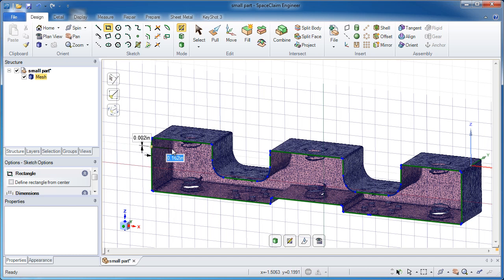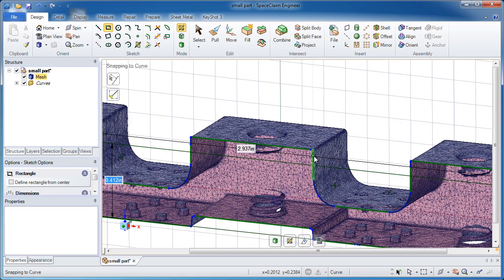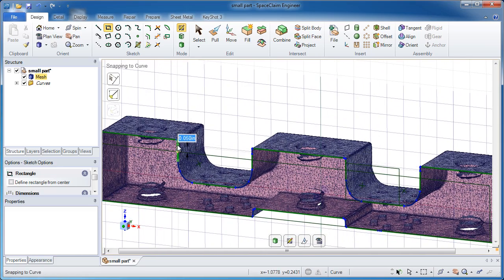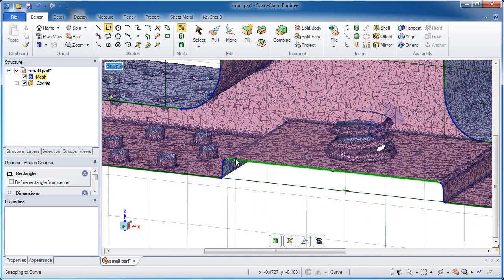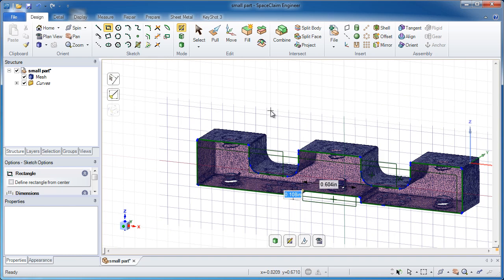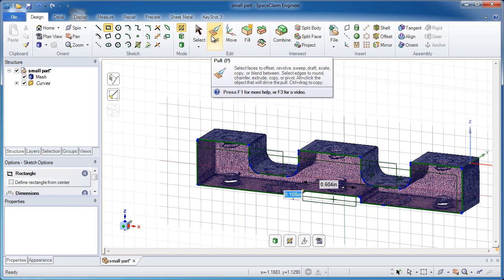I'm going to start by drawing a couple of rectangles just around the perimeter. Both points are actually going to pick on the green edges, but I'm not looking to get something exact quite yet. Just a rough shape, and it doesn't really matter, for that matter, how close I am. 4 rectangles total, one for the large body itself, and then 3 rectangles for the 3 different cutouts. This one over here, let's just make a rectangle that looks like that, so it's not even extending to each of the edges. So you might be wondering, with something this rough, how is it possible to construct something accurate